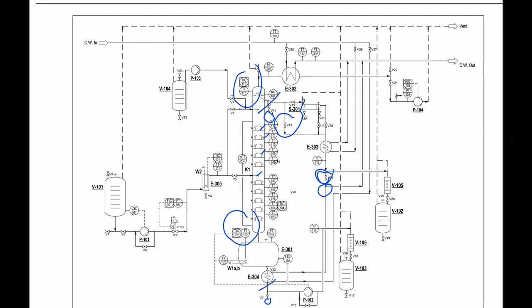Okay, then after all the samples are collected from the top product and bottom product, you can record the refractive index of the product samples into the data table.